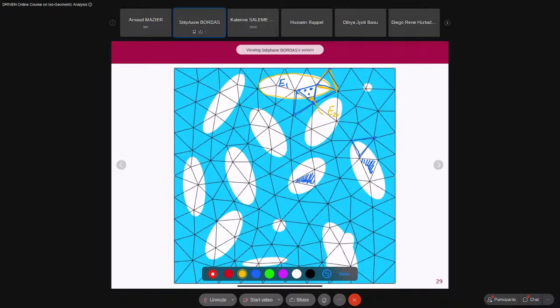Because if this is the displacement field and this is the distance, and for example we plot along this direction, x, then that is what you would see. You would see no kink. And the reality is that you should have a kink. So you should have, let us say, a slow increase first, because let us imagine that E1 is less than E2, and then a faster rise. So this is slope E1, and this is slope E2. So here you need a kink.